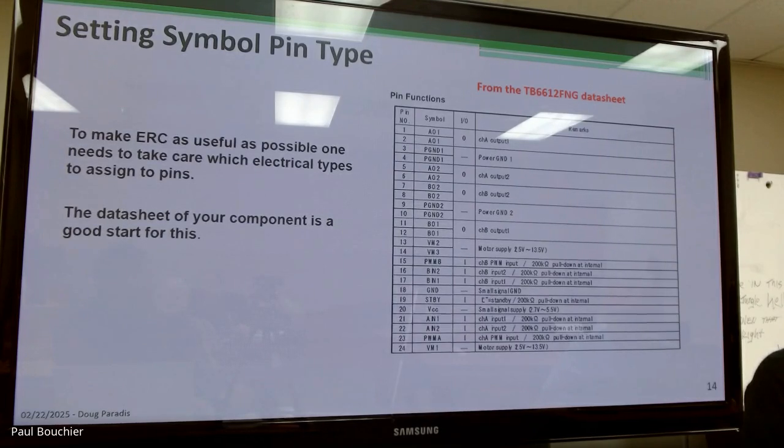So it says the A output 1 and A output 2. The reason why they have two A01s and two A02s on this pin is because this is the chip. This is not the module. This is the chip, and on the chip, to dissipate heat, the output pins are actually carried over to 2 pins. But you can see it labels them as outputs.